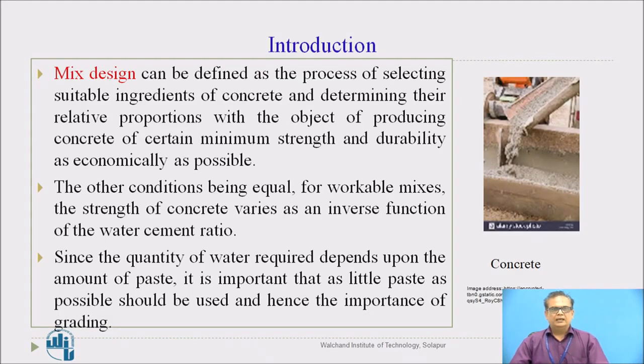Mix design can be defined as the process of selecting suitable ingredients of concrete, remember, and determining their relative proportions. And what will be the object? The object will be producing concrete of certain minimum strength and durability as economically as possible. Economy is also important, remember. So determining the proportions of ingredients of concrete is mix design.